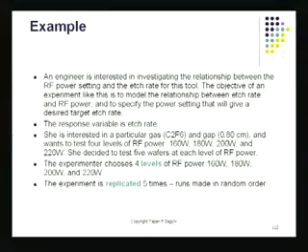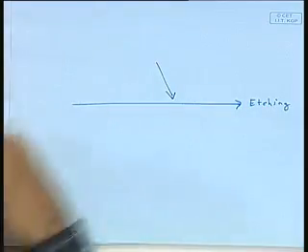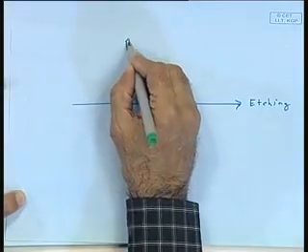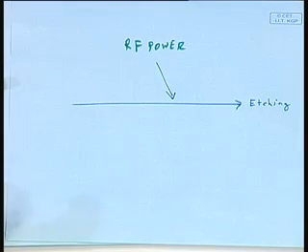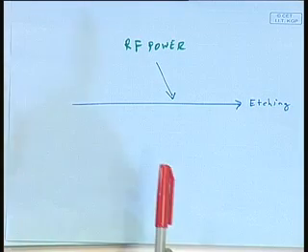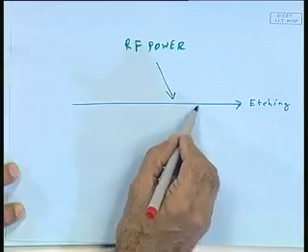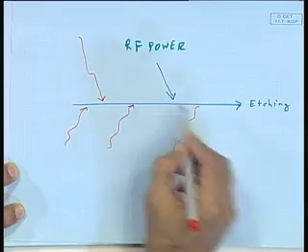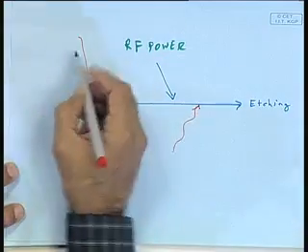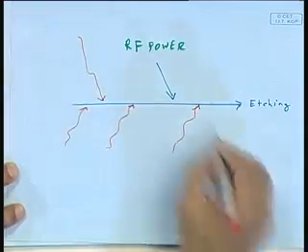Now what we are going to be looking at is the RF power. This is the radio frequency power which is applied on the system. So that's going to be one process variable. I'm going to be putting that down here as a process variable, and that's going to be RF power. That's going to be my process variable. Everything else in the system is going to be treated as noise. There may be a whole bunch of other factors that also could be affecting this etching quality, but I'm going to be treating all of them as noise. So these are all going to be noise factors.